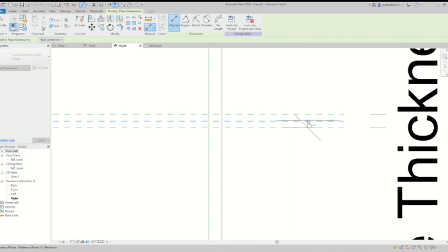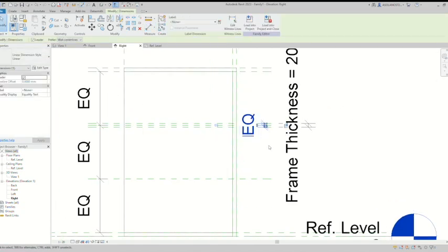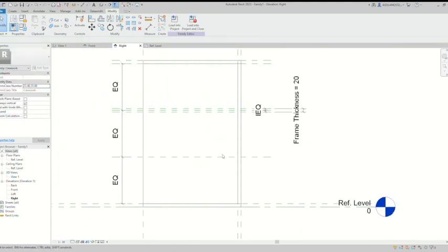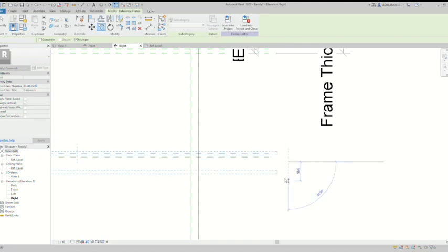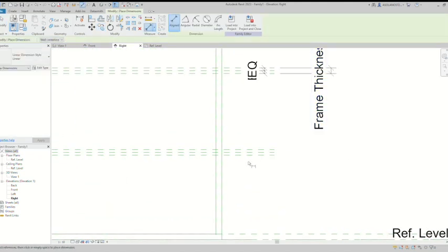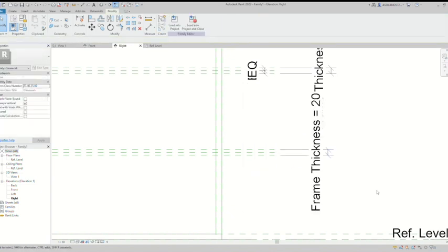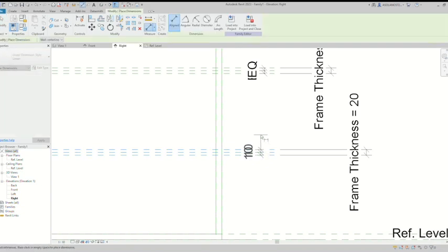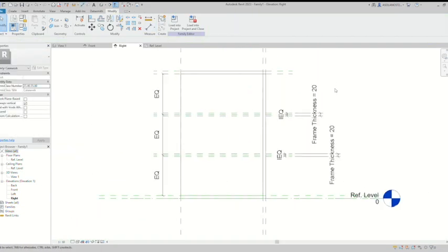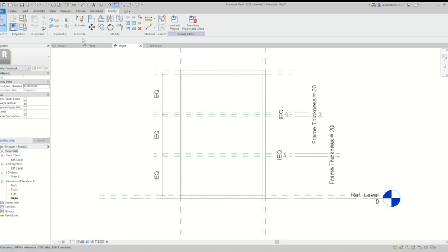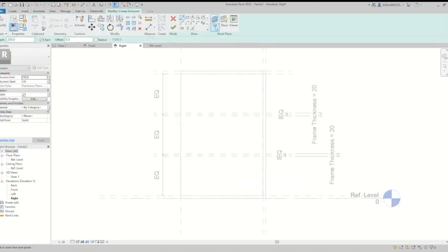When you move or change the distances, widths, depths or any dimension of the cabinet, the shelves are gonna be located regularly inside the cabinet. For this process we have to create more reference planes and add parameters in order to specify this kind of parametric element inside the cabinet that we are creating at this moment.